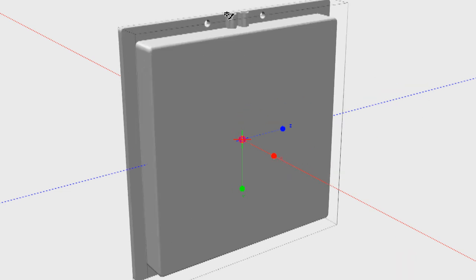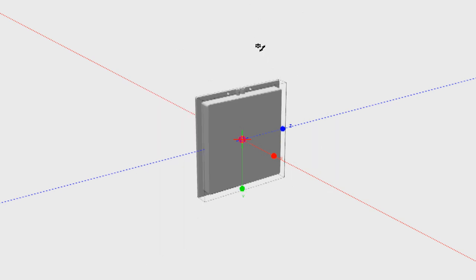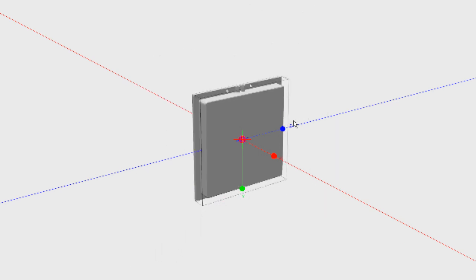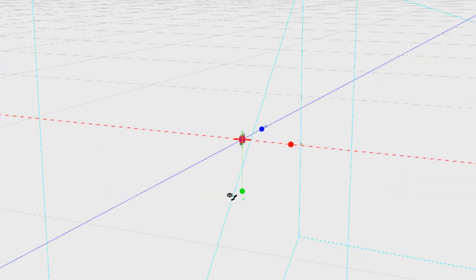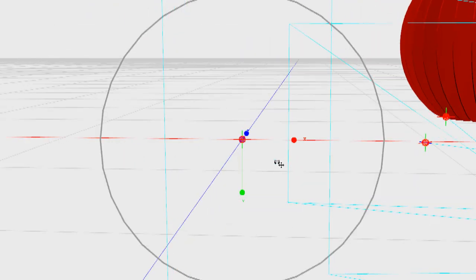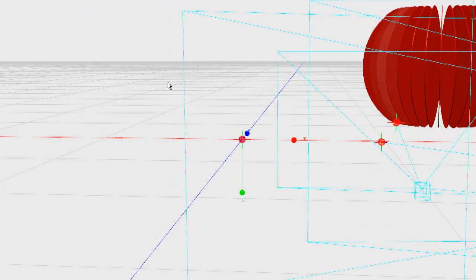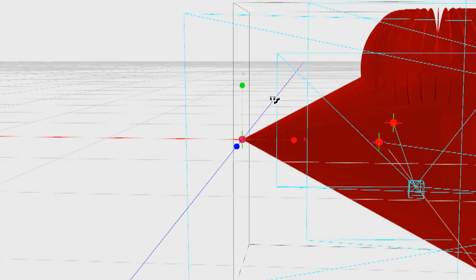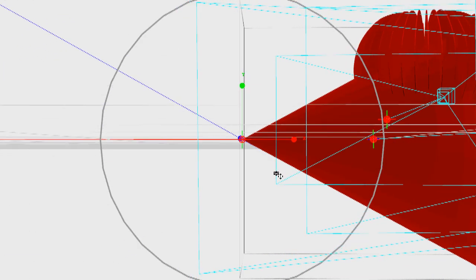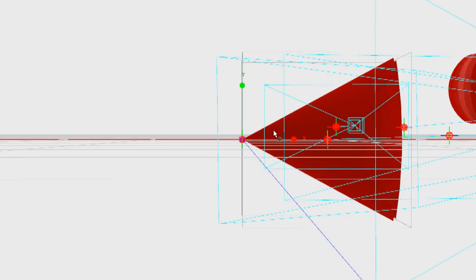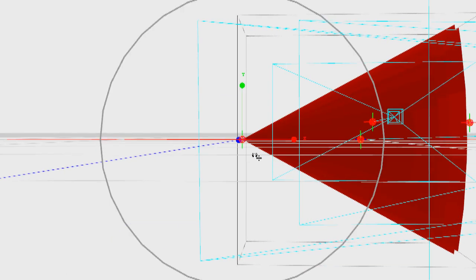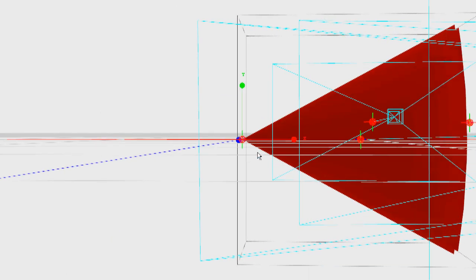Now you'll notice they have two cables coming out of the diversity antenna, because it's actually got two antennas built inside rather than one. So this is a flat patch, 11 decibel gain. So let's have a look at the pattern for that. Let's go for BAM. So as you can see straight away, what we'll do is we'll move the plane out of range for the time being. What we can see is that it's a cone shape.